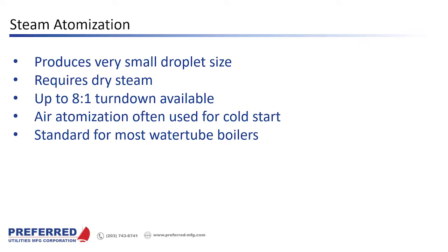So okay, moving right along. A little bit of a deep dive on steam atomization. It produces very small droplet sizes. It's probably the best form of atomization for clean combustion if you can get dry hot steam. You can get up to 8-to-1 turndown with steam atomization.